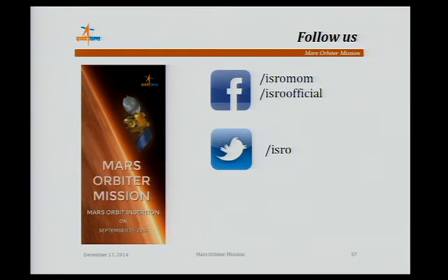Basically, we define all the elements of software, with different layers like the interface layer, application layer, and the remaining interfaces related to the application layer. Like that, a layered architecture is there, and a round-robin type of scheduler, which executes tasks periodically in a time interval manner, a time synchronized system. We are not using interrupts except for things like the watchdog timer.